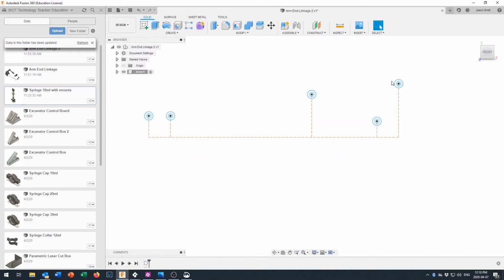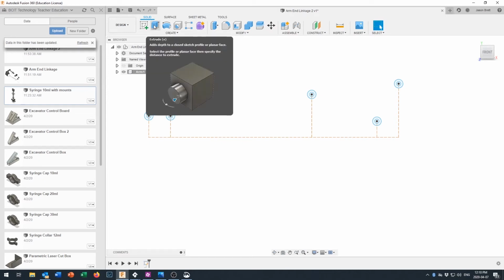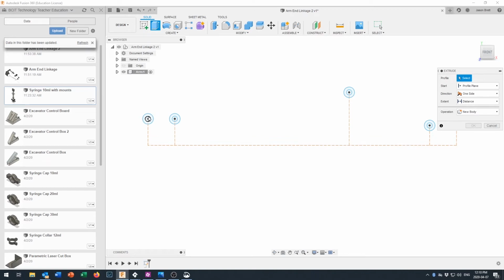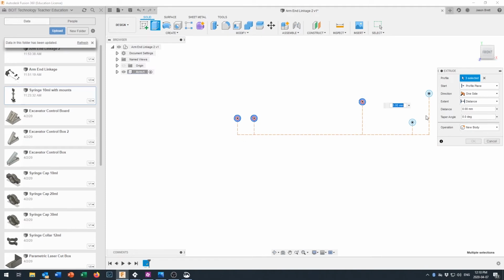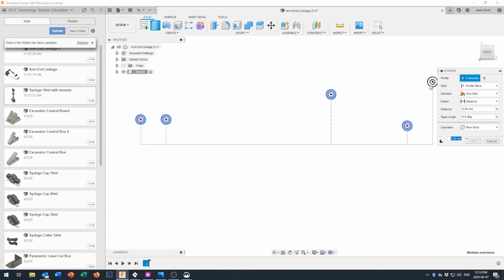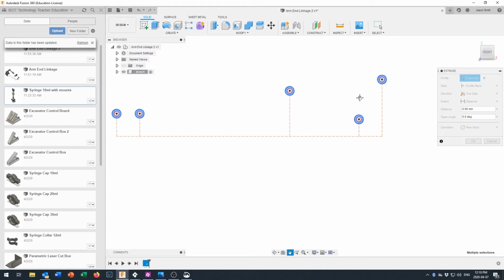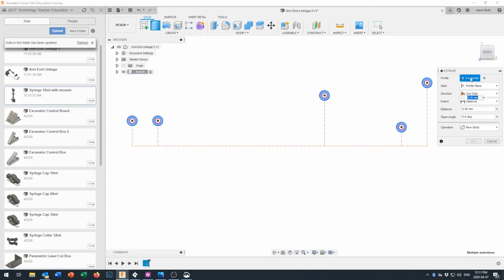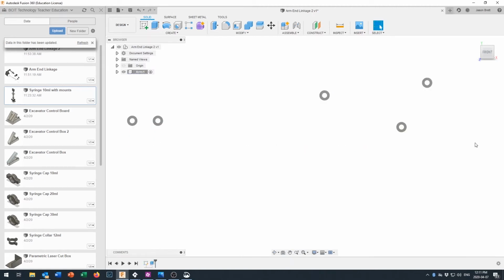Let's finish that sketch right now. And now let's make these parts real by bringing them into the three-dimensional world by doing an extrude. We're going to pick each of the outside diameters. Remember to leave that little hole in the middle for our joints to format. Did I get them all? There we go, 5 of them have been selected. We are going to extrude them out 3 millimeters, which is approximately the thickness of the MDF that we're working at. Right now, this is just a representation of the profile of that arm so that we can work out the geometry of that arm.